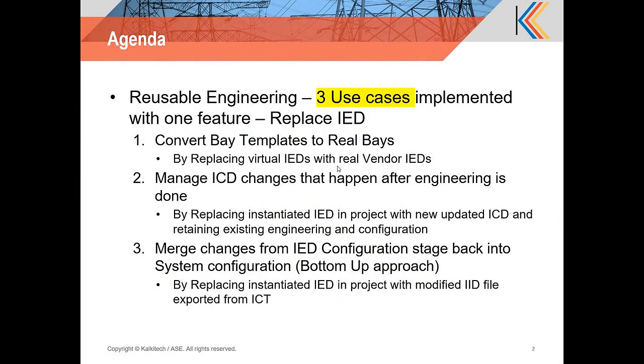There are three use cases which are commonly encountered in utilities with regard to SCL engineering, which are all implemented in SCL Manager using one feature, that is replace IED. The first of these use cases is about bay templates. Bay templates are a way where utilities can pre-create engineered bays using vendor-agnostic dummy IEDs, that are virtual IEDs.